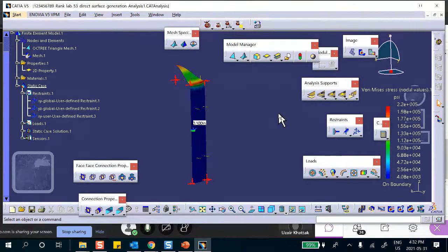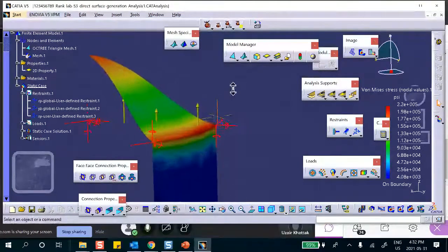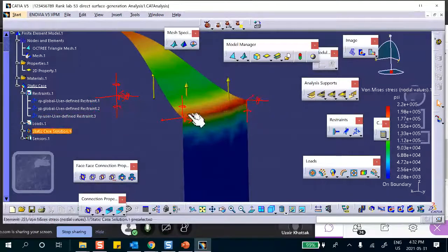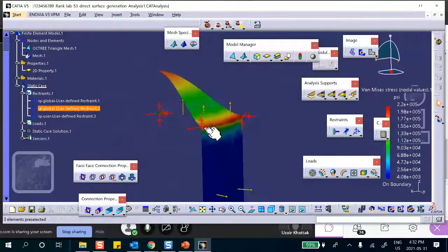200,000. Yield strength of the steel is 30,000. This is 10 times bigger. We know that. Okay. Now, a few things. First of all, this is all garbage. This red stuff is all garbage. And this is all garbage. Because if you really want to know what happens to a tank like that, at that juncture, a lot of nasty things will happen. That stress through the thickness being 0 is not applicable here.